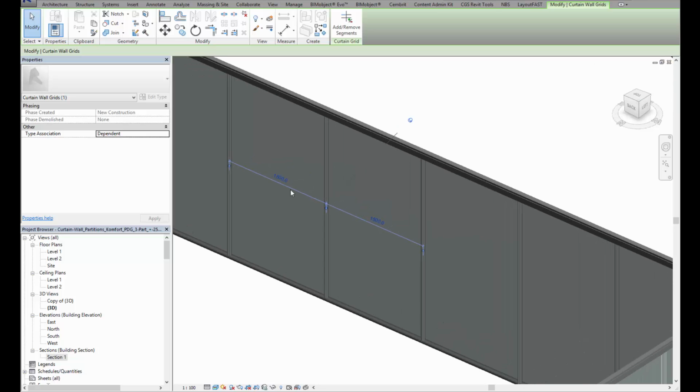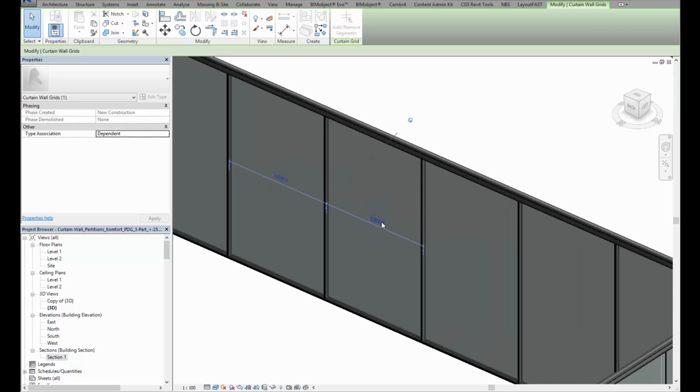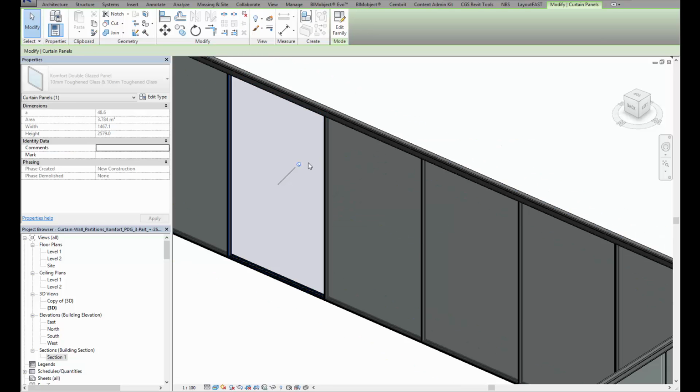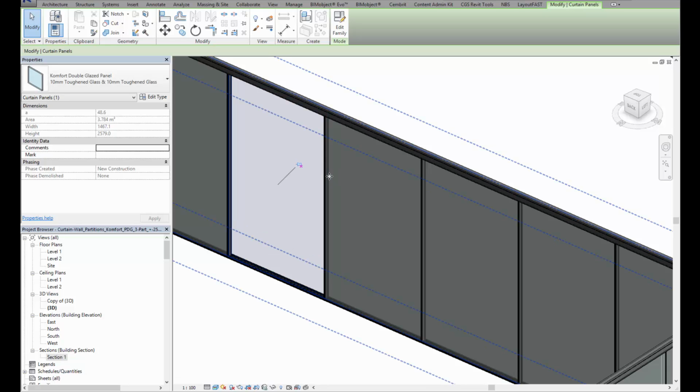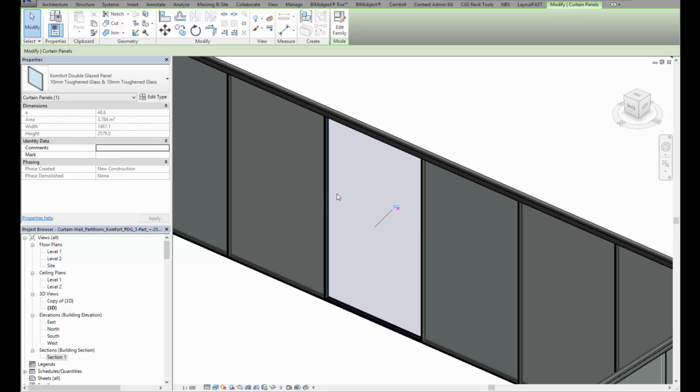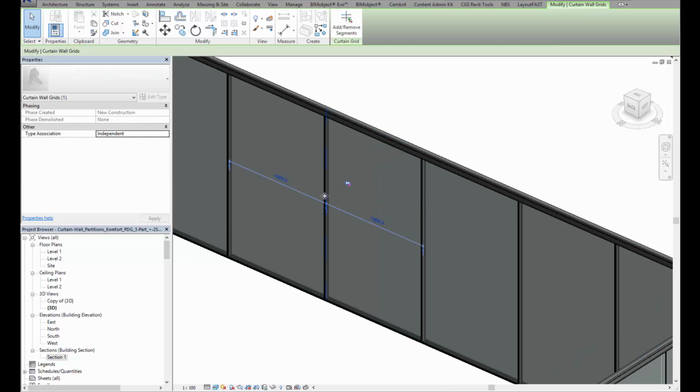What I can also do here is that you can see I've selected 1500 to 1500. I can uncheck that as a distance, so let's just go uncheck the panels. So it's important using this system is that you can lock and unlock the system, and it is a bit fiddly. We are working within the constraints of what Revit allows us to do.